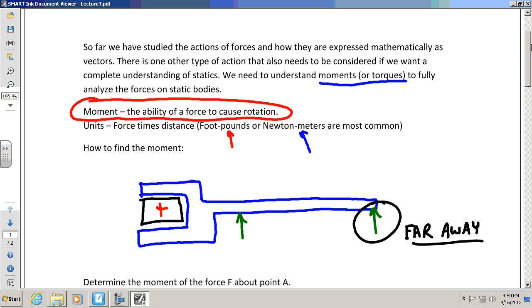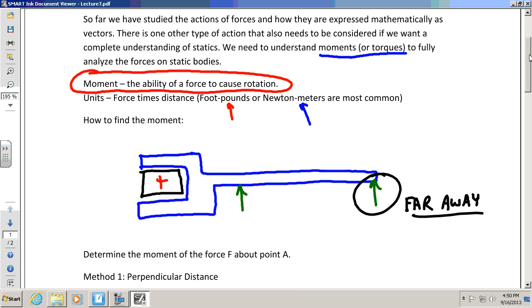Okay? All right? So that's going to help you there. So that's the key I want you to remember now. Think, a force times a distance gives me the moment, and I can see that the further distance I'm away from the axis of rotation, the more moment I'm going to get. That's just intuitive if I'm tightening something or I'm loosening something. Okay?